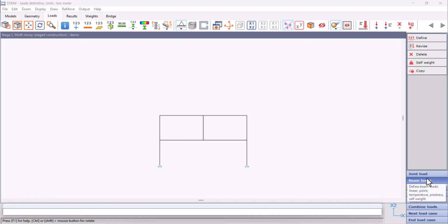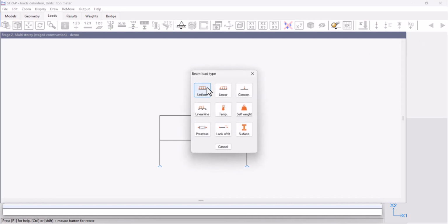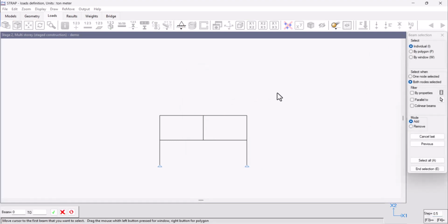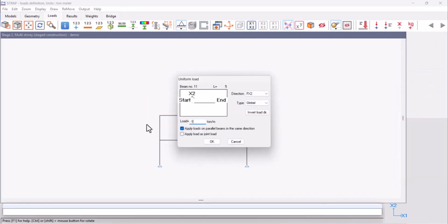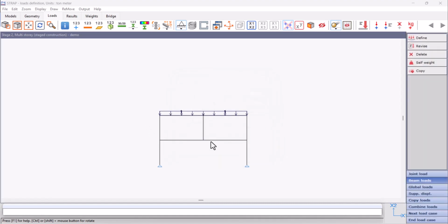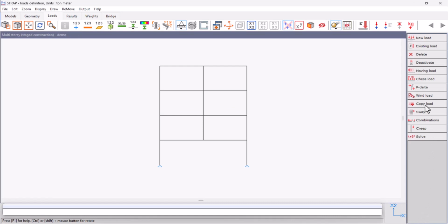In the next construction stage, another floor is cast, but the loads from the bottom floors are not transferred to it. The bottom floors have already been subject to previous deformations and stresses, to which the next construction stage adds its own. The self-weight of an additional floor is redistributed between itself and the existing elements in the structure, and so forth.